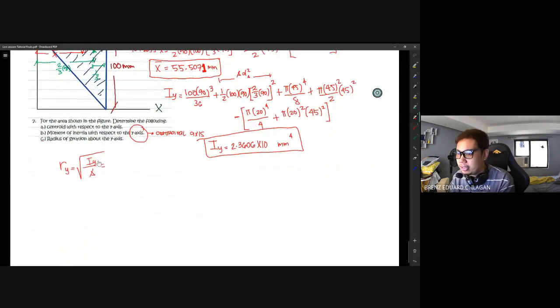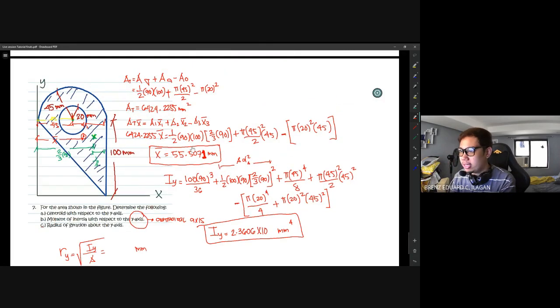So, ang unit nga natin dito is units raised to 4. Yung baba is units squared. So, kapag kinansel mo siya, ang matitira sa iyo is unit squared na lang, di ba? Kasi 4 divide 2. So, 2 na lang. And then, naka-square root ka pa. So, tama na ang unit niya is in units lang or radius talaga siya. Radius of gyration. Okay? So, paipindot na lang nito. Direct substitution naman yan. Kinukuha natin sagot dito at saka yung total area.